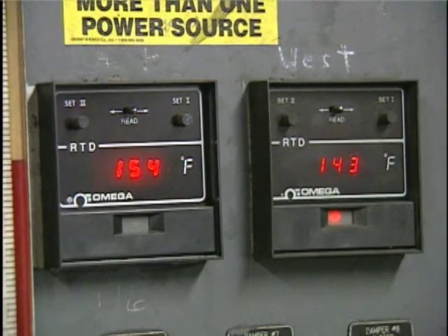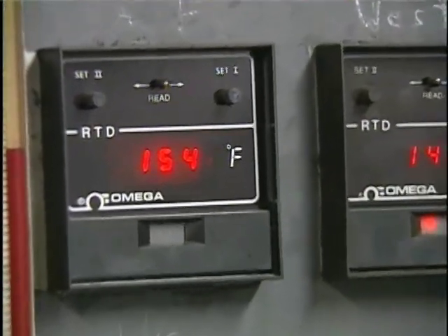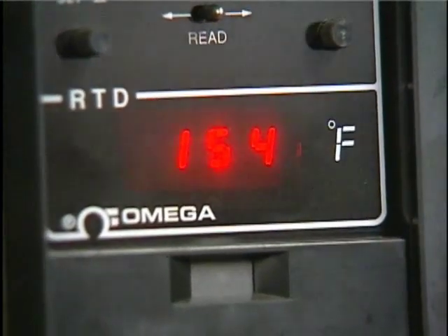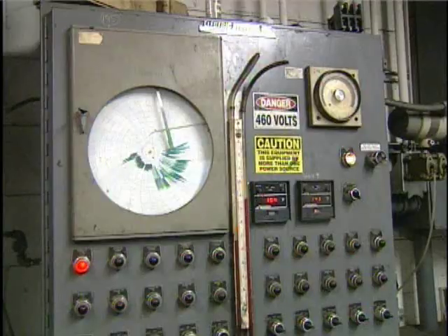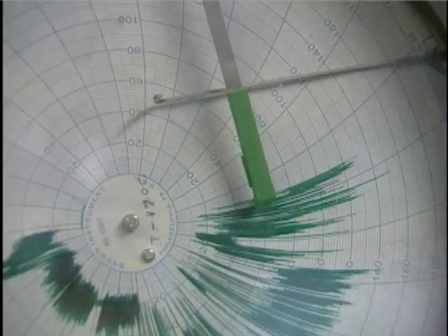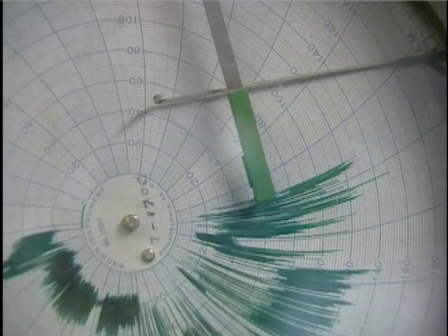The inlet and outlet temperature of the collector should be checked. The inlet temperature should be compared to the temperature limit for the fabric being used. Frequent exposure to high temperatures can damage the fabric and cause holes to develop. Low inlet temperatures could result in acid, moisture, or organic vapor condensation.